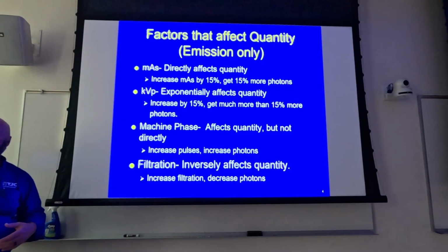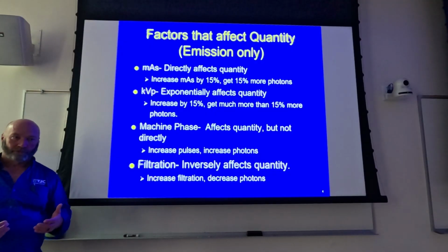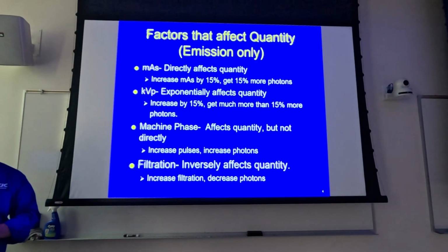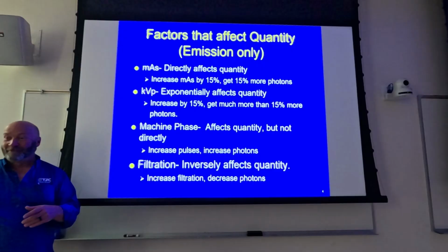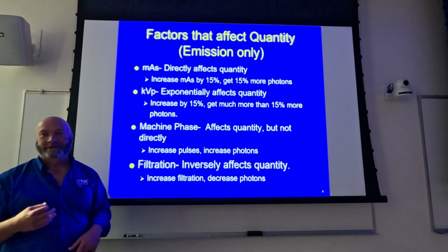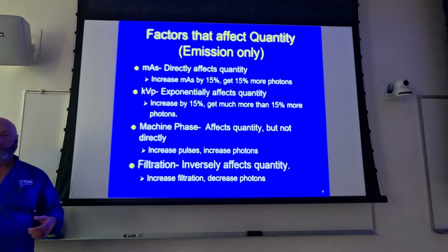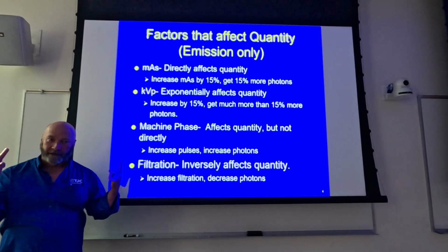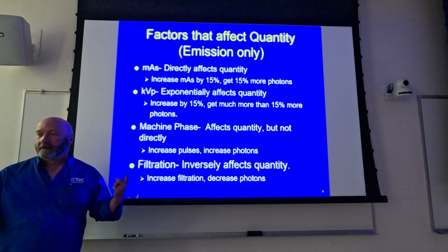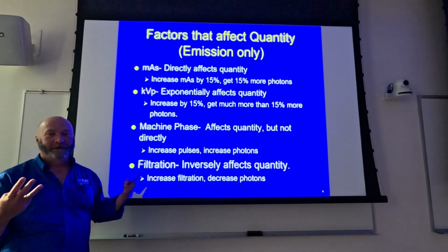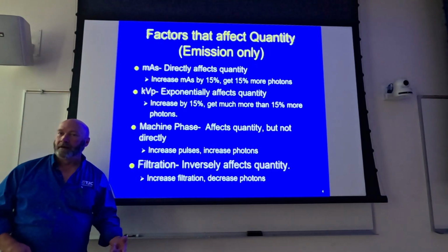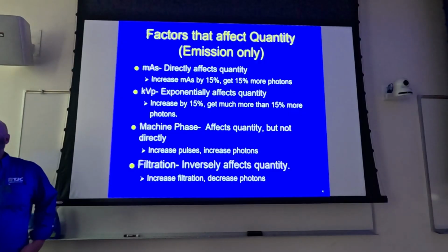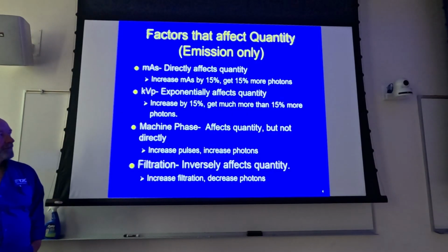If you go from single phase to 3-phase, you get a greater output from the X-ray tube. You remember how much it is? 2. In fact, very good, factor 2. I knew somebody was going to say 3, which would just be too logical. Single phase, 3-phase, factor of 2. Yeah, it should be 3, but it's 2, right? So if you go from single phase to high frequency, it's about 2.5. So it's slightly more, not significantly more, but it's slightly more.